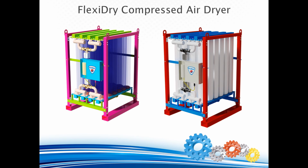Because of the regenerative element of this style of dryer, modules are always assembled in pairs or multiples of pairs, so one set of modules can perform the drying function while the other set of modules can undergo the regenerative cycle. For example, a pair of Flexi 4U modules will contain 8 vertical tubes filled with desiccant, but only 4 tubes will be performing drying, while the other 4 tubes will be undergoing desiccant regeneration in an alternating fashion. This pair of Flexi 4U modules is the smallest FlexiDry configuration with a 275 CFM flow rate.